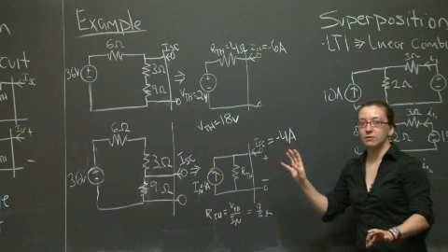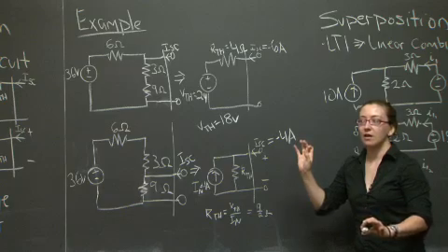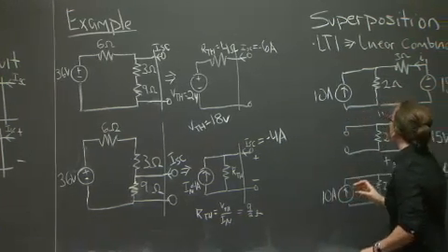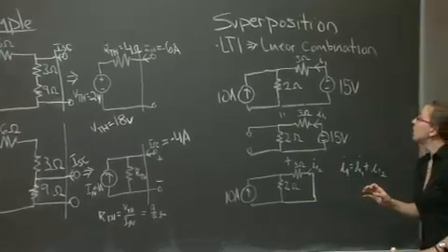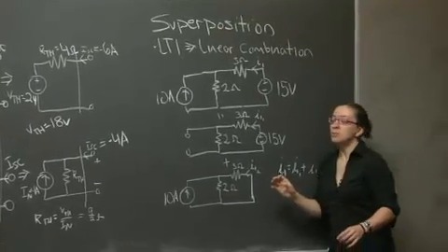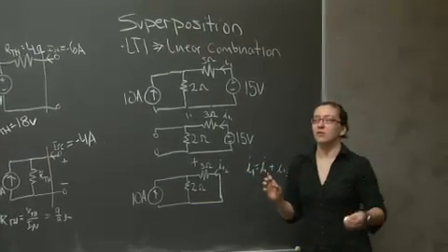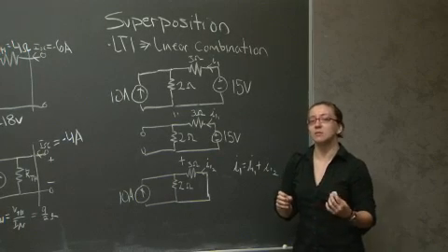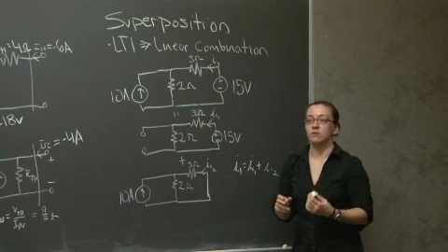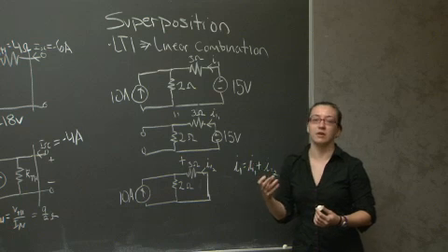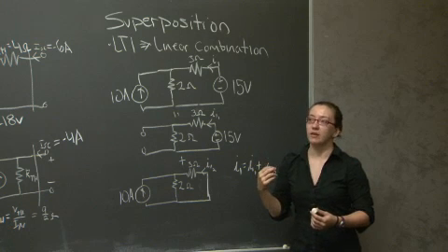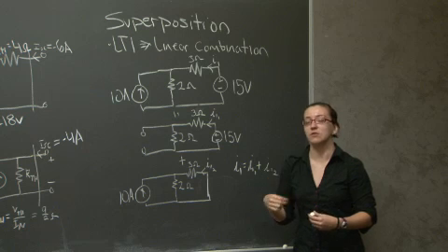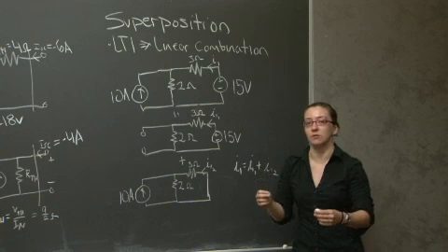That covers Thevenin and Norton equivalents. I'm going to talk about superposition really quickly. Superposition is yet another circuit solving strategy. It falls out as a consequence of only working with LTI components, and it means that in order to solve for a given component current or component voltage, you can actually find it by taking the linear combination of every contribution as a consequence of independent sources.